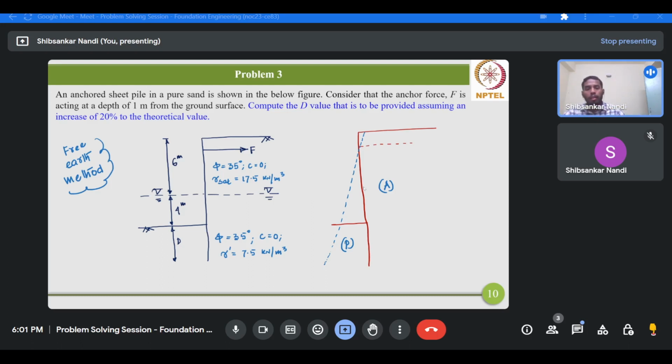We'll not discuss in much detail the net earth pressure distribution, because for this problem the deposit is purely sand, and this kind of problem we already solved last week for the cantilever sheet pile wall. So we'll first draw the active earth pressure, or net earth pressure distribution, up to the dredge level for the right hand portion.